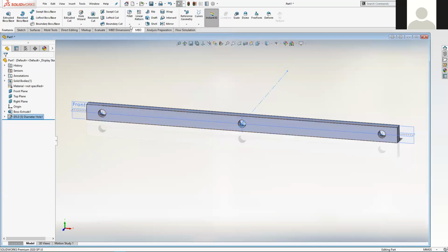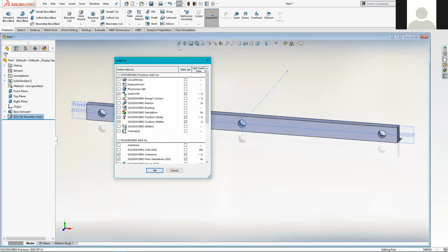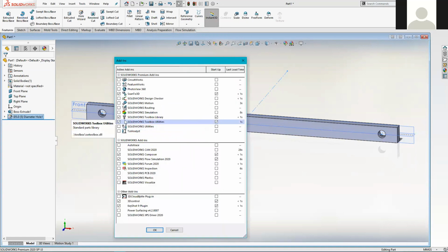So you can see here, I can hide that tab. So if you can't see it there, if you go into the Tools menu and look down at the bottom, there's the same option there, add-ins. So either way, you get into it through the tab or you go into the actual menu version here. But essentially what we want is that option. SolidWorks simulation needs clicking on.